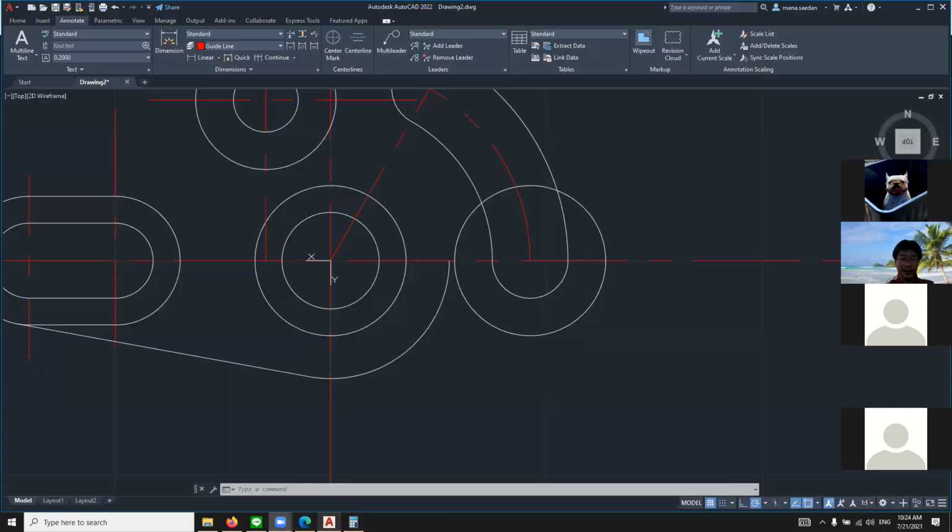All right, so we create the circle. There may be a few other tricks, but I use circle only to make it easier. Go to circle. The default circle option is specify center and radius. We don't want that. In this case, we want tangent, tangent, radius. So far, it has that option. So we click this one.